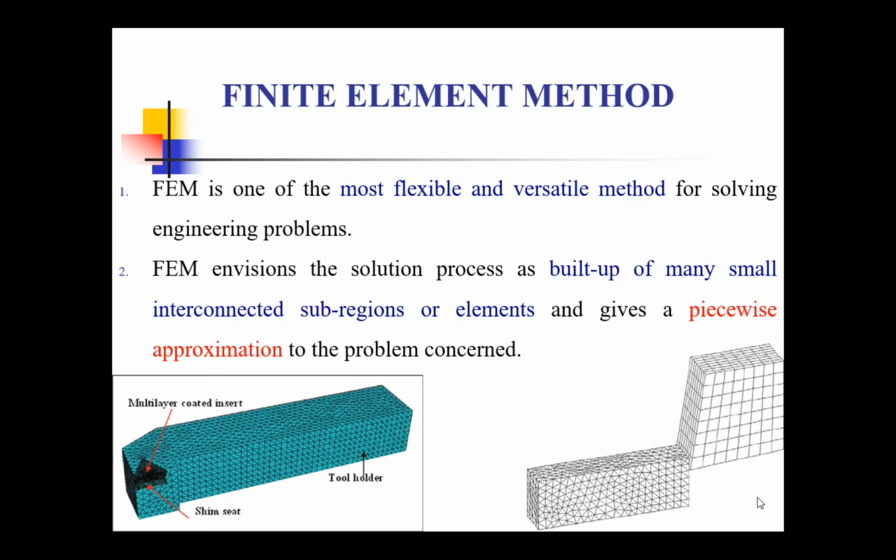Here you can see they have modeled the cutting tool holder. That is the total domain, which is discretized or divided into finite elements. If I want to determine the deformation of this tool holder, then first of all I have to determine the deformation at each and every element. Then by integration from the single element to the total domain, I determine the deformation. That is the basics behind FEM.